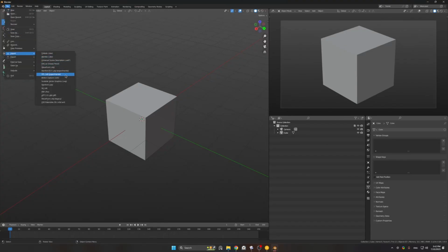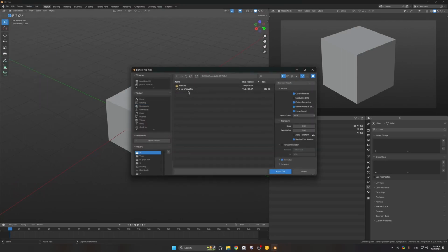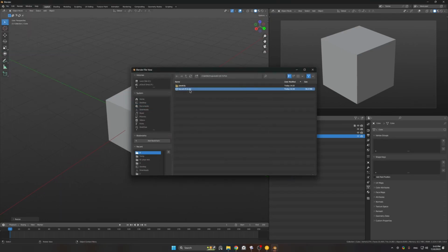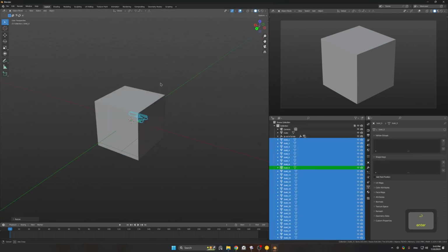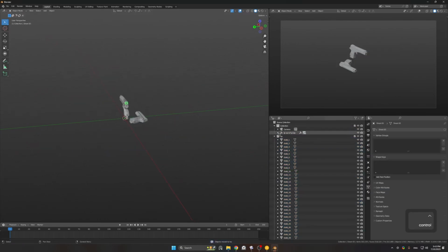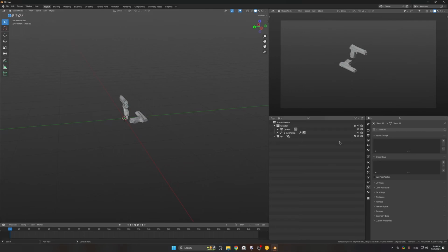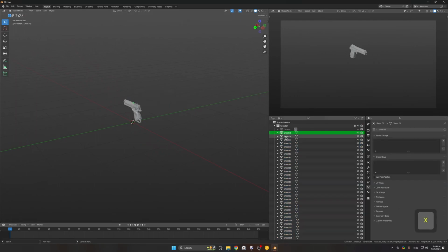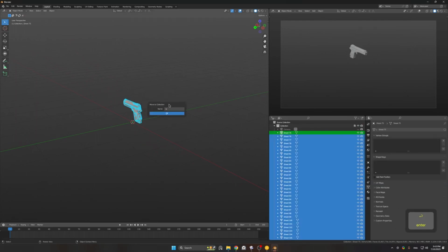Now open Blender and import both low poly FBX and high poly OBJ into our scene. Make sure to add them into separate collections. The Pixies export comes as a system of parented bodies. So to make it a bit easier for myself, I unparent everything while keeping the transform right away.